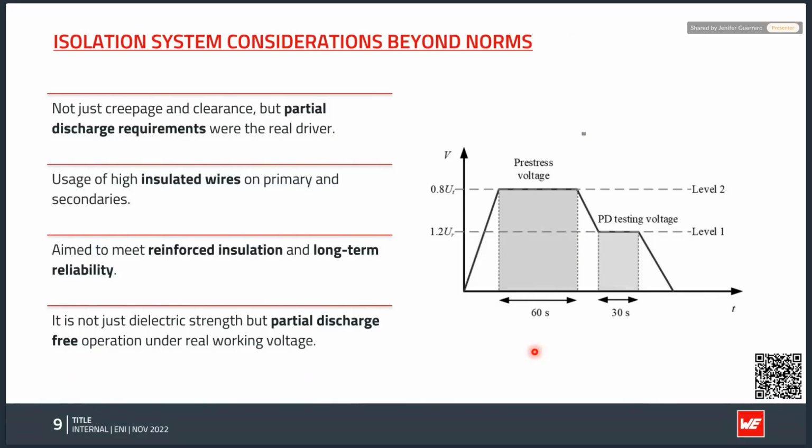People may not know, but partial discharge, or PD, if you have heard it called that, refers to microscopic electrical discharges that occur when, for example, we have localized electrical field stress and it exceeds the breakdown strength. So we don't want that.